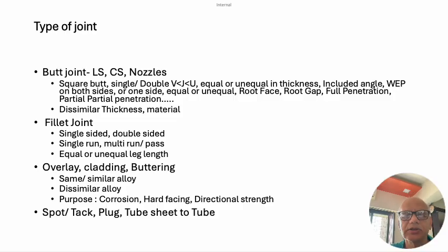But if you have processes like plasma or activated TIG, concentrated TIG, or very high-end processes like laser and EB welding, you can penetrate even a square joint but at much higher thicknesses, going from 5 millimeters to 10 millimeters. And if you have a really super high kilowatt rating on your EB welders, then you can go to 70 to 80 millimeter thickness also.